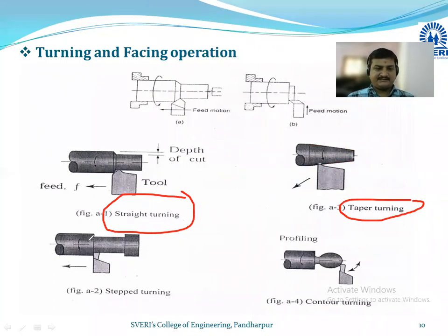थर्ड थिंग इट इज द स्टेप्ड टर्निंग. हा जो तिसरा भाग आहे हा आहे स्टेप टर्निंगचा. यू कॅन सी हिअर, इथे एक स्टेप तयार केलेली आहे. कॅन यू सी द स्टेप? Yes, sir. मध्ये एक खाच निर्माण केलेली आहे. कशासाठी खाच निर्माण करतात? की बऱ्याच वेळा मोटरमध्ये तुम्हाला बेल्ट वगैरे तिथं फिट करायचा असतो. तो बेल्ट सरकला नाही पाहिजे. तर बरोबर जेवढी तुमच्या बेल्टचा पट्टा आहे त्याची जेवढी लेंथ आहे तेवढी इथं स्टेप तयार केली जाते. आणि त्याच्यामध्ये एकदा जर तुम्ही बेल्ट टाकला तर तो बेल्ट जो आहे तो त्या तेवढ्या एरियाच्या बाहेर येत नाही.